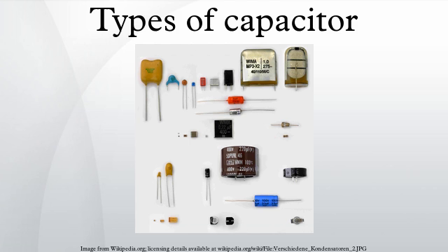Rated and category voltage. The voltage at which the dielectric becomes conductive is called the breakdown voltage, and is given by the product of the dielectric strength and the separation between the electrodes. The dielectric strength depends on temperature, frequency, shape of the electrodes, etc. Because a breakdown in a capacitor normally is a short circuit and destroys the component, the operating voltage is lower than the breakdown voltage. The operating voltage is specified such that the voltage may be applied continuously throughout the life of the capacitor.